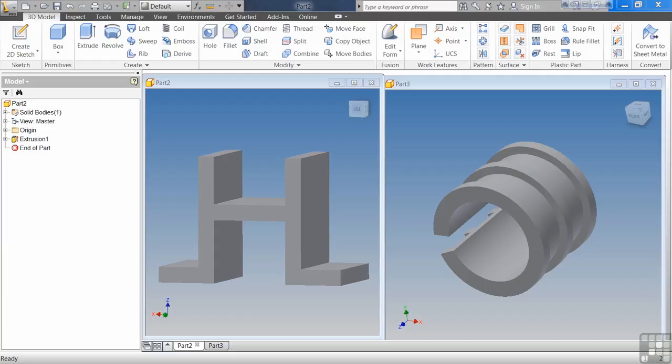What this really means is, are we creating geometry or are we reducing geometry is what it boils down to. So things like extrudes, revolves, sweeps, lofts, we're creating geometry, so we have to have a sketch. For modifying geometry, then it's a placed feature.